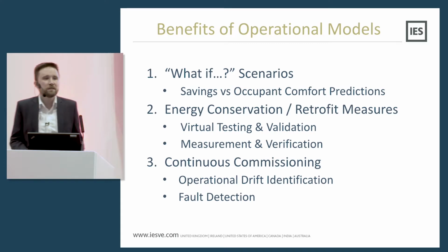So why would you want an operational model? Why do you need a model that's a close match to your real building? Well, it enables you to perform what-if scenarios. What if I lowered my heating set point? What if I ran my AHU for 3 hours less per day? What if I turned off my chiller to avoid peak demand tariffs? What impact will that have on energy, cost, and comfort? So you can perform all these types of analysis with a model without using your real building as the guinea pig. You can also evaluate maybe retrofit measures.